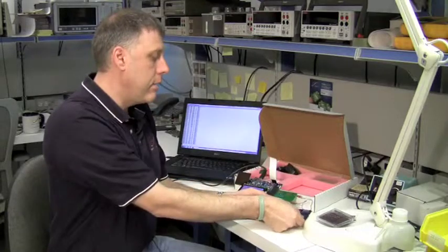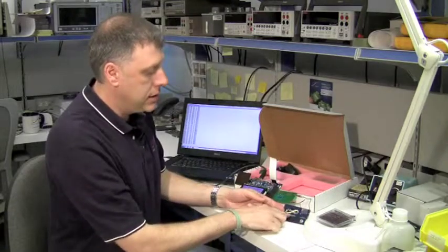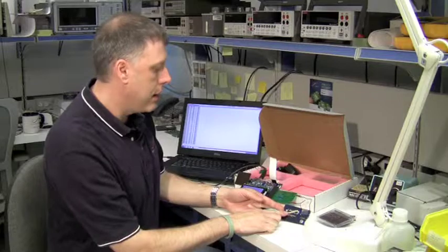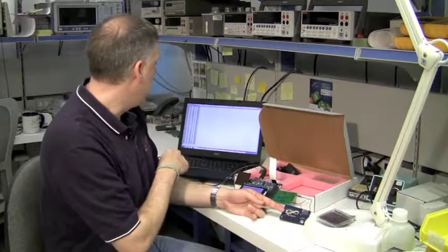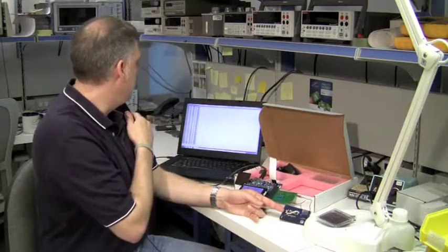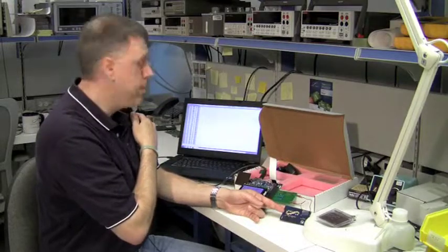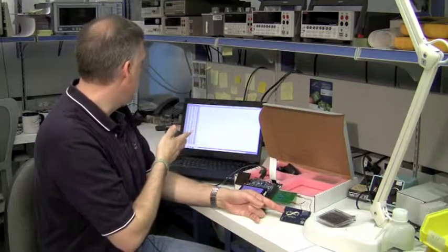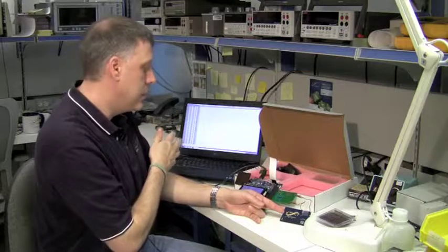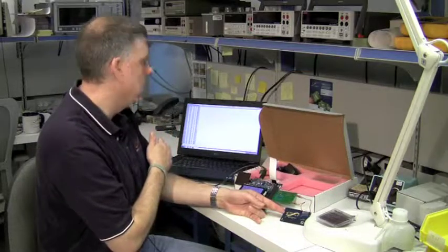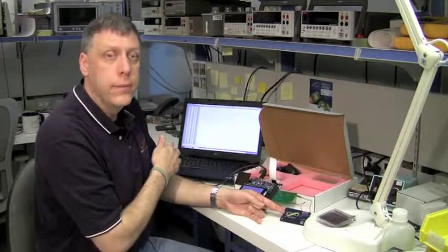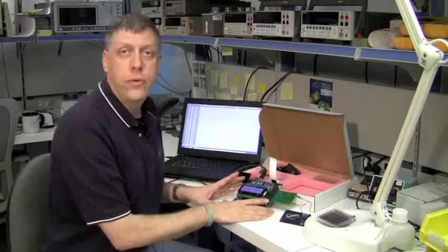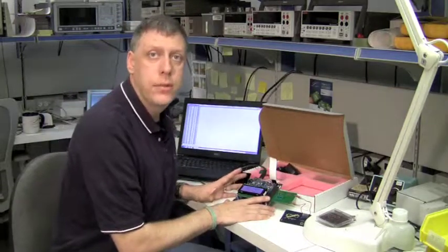So here I can activate my card, and you can see these LEDs are blinking here on the card right now. So the card is currently running from the MEC, and I can see the voltage that the battery is dropping to while it's under load. So it's dropping down to around 3.96, 3.95 volts or so during the activation of the card. So anyway, that's an overview of the functions and features of our application development platform.